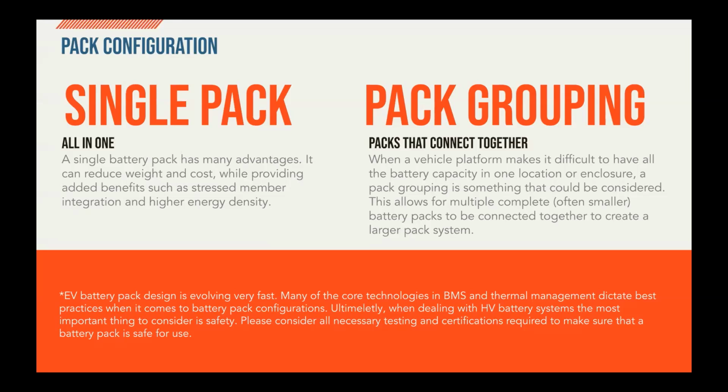So they can be designed as an all-in-one single battery pack within the vehicle system. So the skateboard deck concept typically applies here, where it's one large battery pack that houses all of the power distribution for the battery system, all the cooling, the battery management, and everything in one single enclosure. This is a great way to reduce cost and weight, and also provide potentially added benefits of stress member integration, where the battery pack can be used as a structural member of the chassis to save weight on the whole vehicle platform.